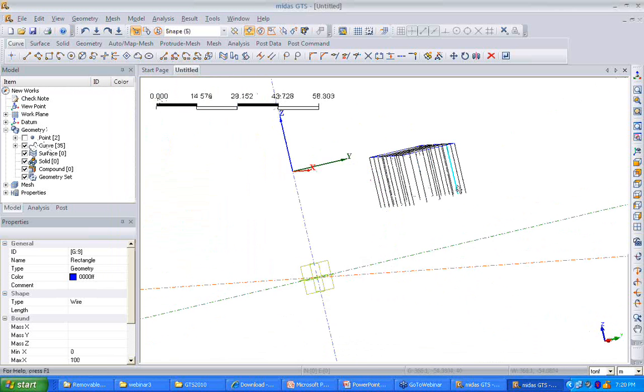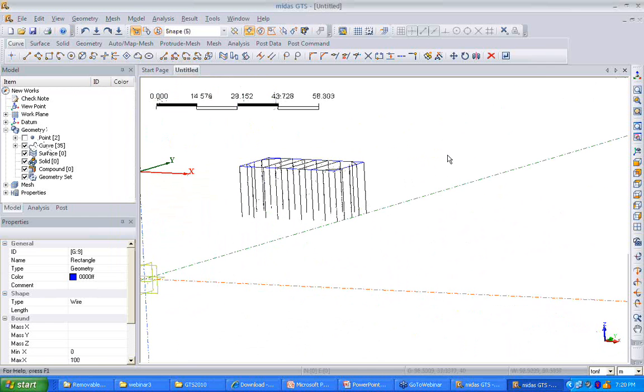So we revert it back. Let's hide this thing. What we are going to do is, I will first intersect this wireframe with the piles, so that all the piles will have the impression in terms of a point on this wireframe, and then I will make a wire again from those intersected curves. So the newly made wireframe will have the impression of each pile, and then I will extrude that wireframe to represent the excavated layers.